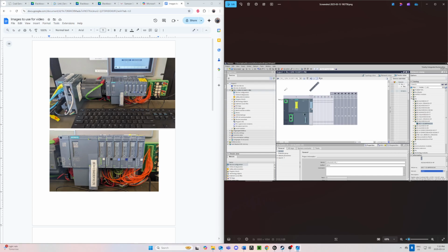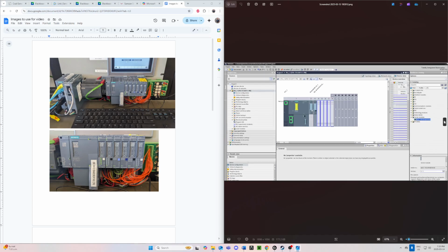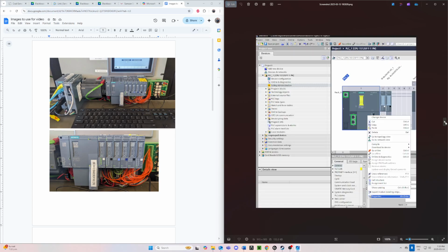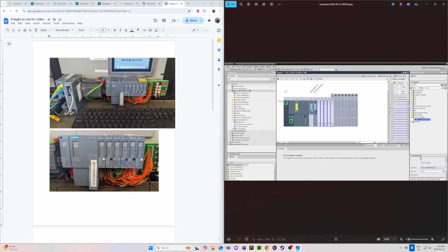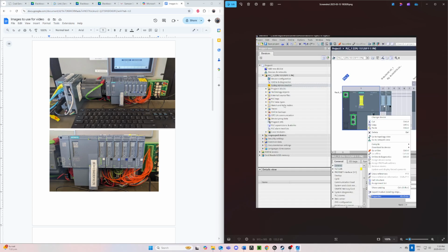After that, you'll be closing that submenu and opening up DQ, which is the output. I for input, Q for output. You'll be selecting the DQ 8x24 VDC. And same thing, it'll be version 1.2. Once you've changed the version, drag and drop it into slot 3. After that, you'll be selecting server modules, and as there is only one, that will be version 1.1. And you will have a complete PLC created virtually after that.